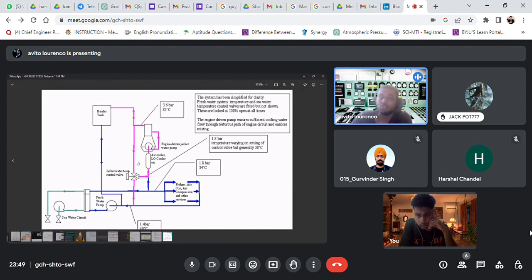This high temperature water gives its heat away to the low temperature water, the blue color one. The blue one, which is again fresh water only, is cooled by the LT cooler with the seawater circuit. So the question now is, why do I have fridges, air conditioners, all of this having this fresh water connection over here?